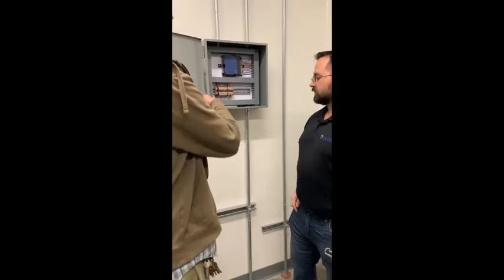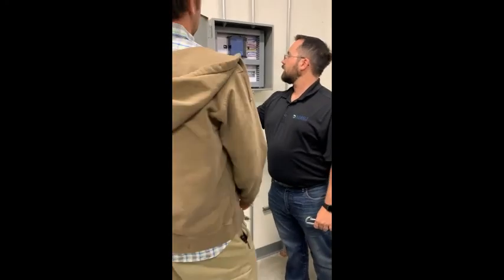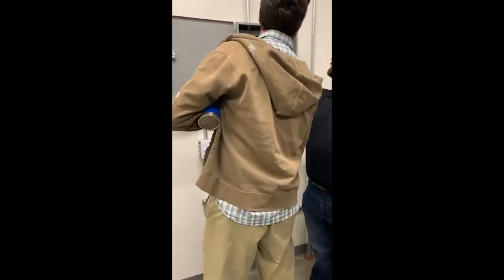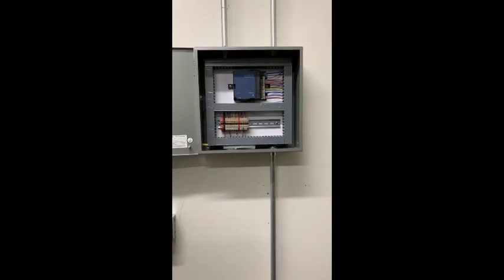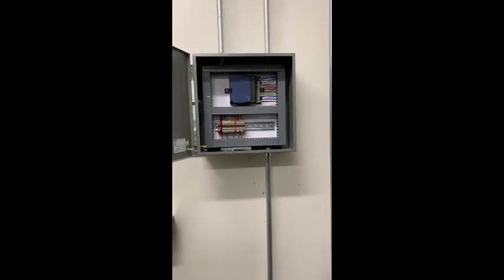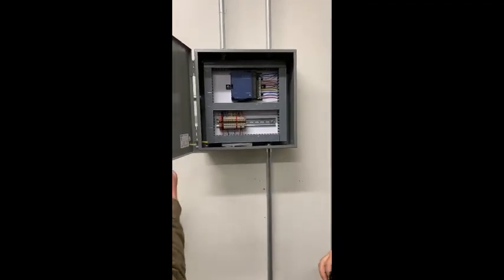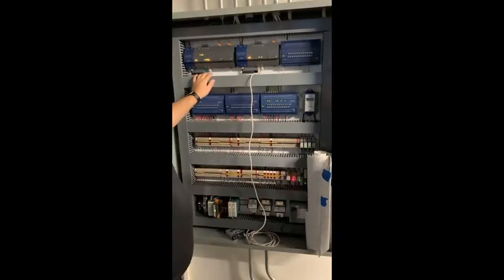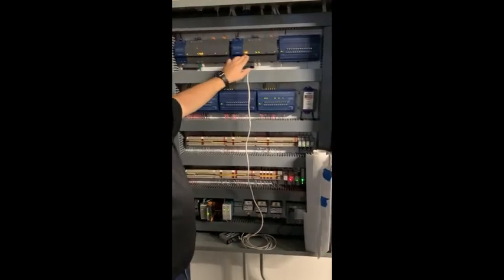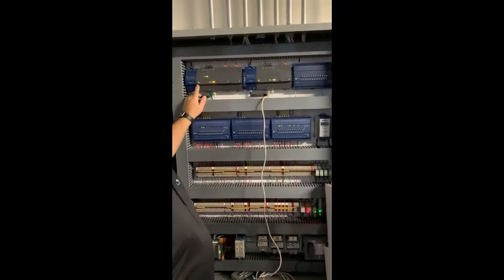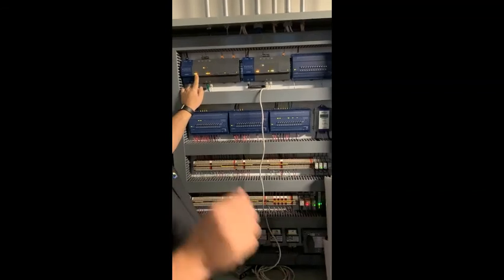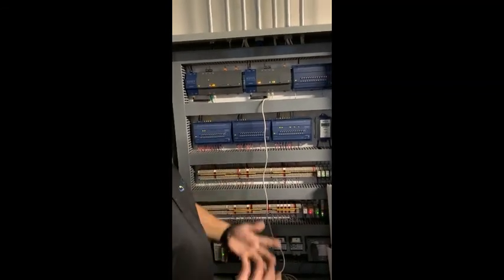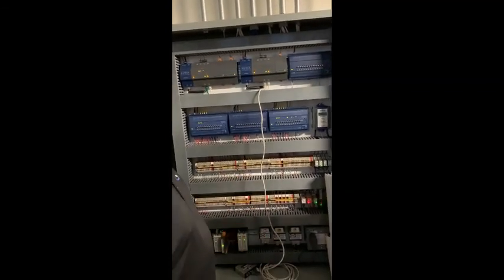So that tells you the sensor plugs in, right? This is the long communication trunk here, and this is the I/O and power. They all get powered from the unit themselves. You'll see that there's a few different lights on the Jace. This is power and a heartbeat. It should blink constantly like that. That shows that the Jace is up and running, normal function.